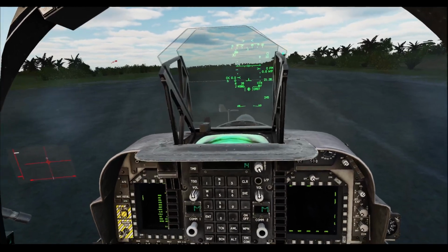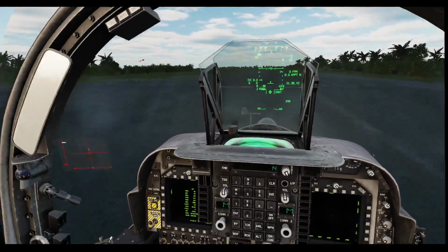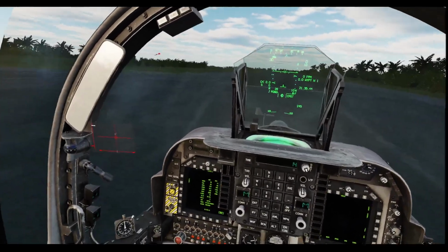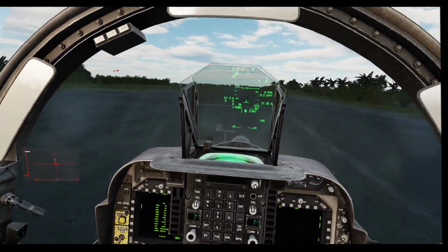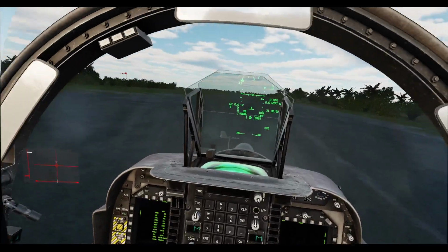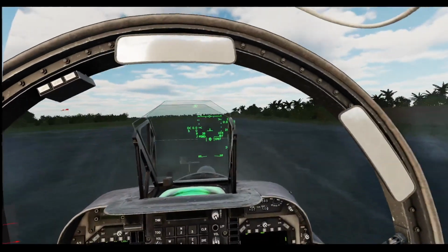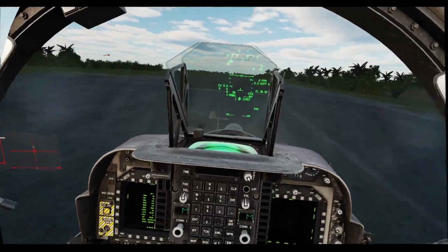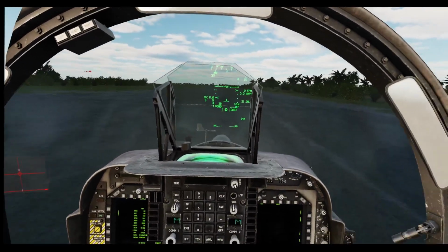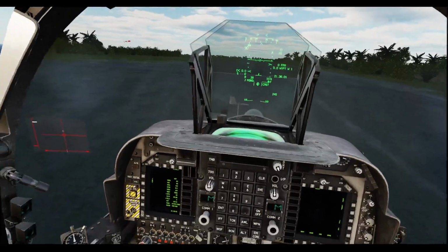So it's important to note this is the only time that you may find that the nozzle angle varies. Generally, it's always going to be consistent. If you're doing a maritime short takeoff, it's going to be 60. If you're doing a rolling vertical takeoff, it's going to be 70. And if you're doing a vertical takeoff, there's going to be no STO stop.